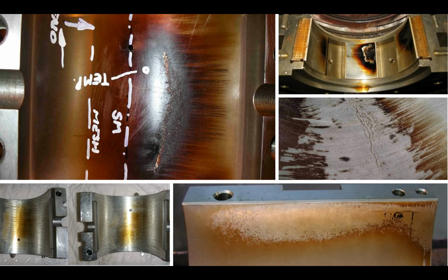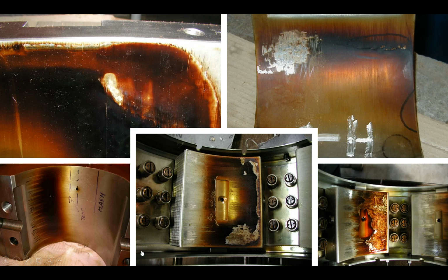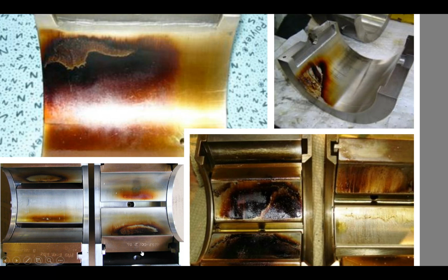We have more examples of this where you can see typical wear symptoms occurring on these different pictures. I'll let you look at some of the typical pictures we have here. Also here, another four or five good examples. Look at the one on the right upper. Also, you will see again the typical wear happening on these components. And like I told you, we have plenty of pictures. Notice again this amber orange color can be present in different ratings, from very light until, like you can see on the picture right down, the black coke deposits on these bearings.